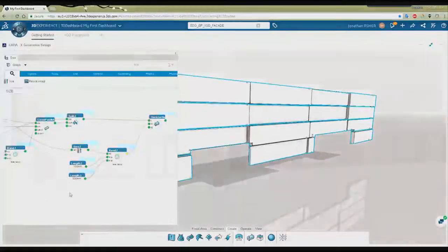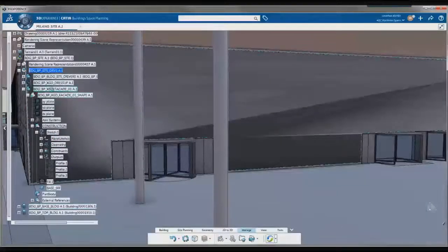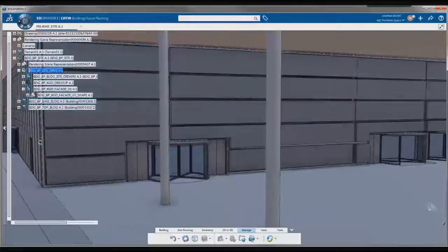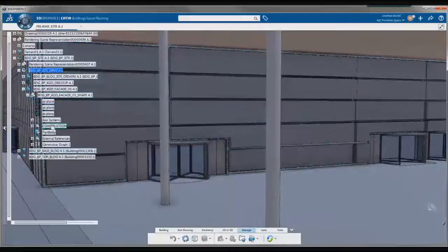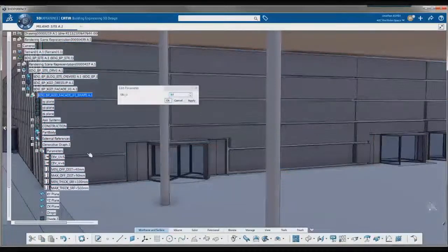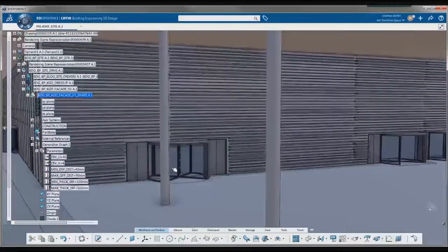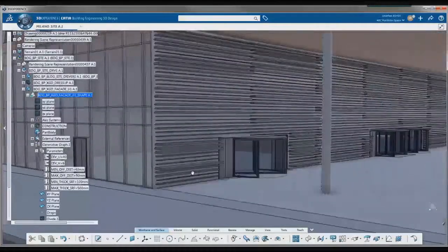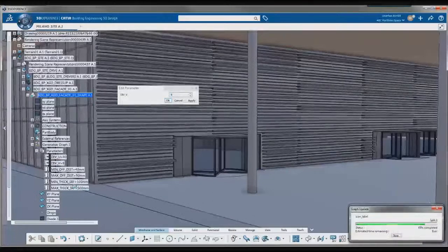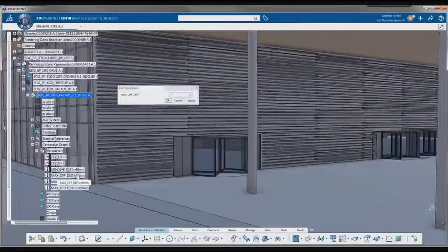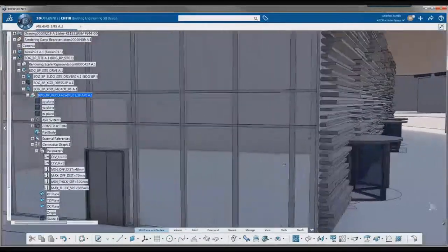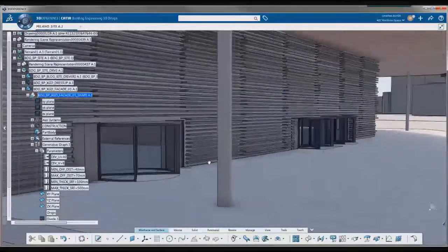And then once we've created this model, we can save it, go back to CATIA, and do a selective refresh. CATIA has automatically detected a change to this part in the database. It's refreshed the model, and now I can continue my design by modifying the parameters that I defined in X generative design. So for example, we'll change the spacing in the U direction of that surface. We'll change the spacing in the V direction of the surface. And you see that the design sequence is updating and producing this geometry for me. So this is one way of collaborating within a unified master model across different phases and project team members.